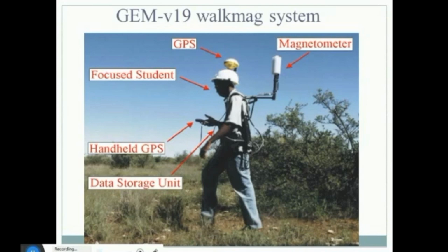Whereas it's the older magnetometer, which you also have, and you also use a pencil, you have to walk 5 meters, put it down, take a measurement. Walk 5 meters, put it down, take a measurement. You can't have anything magnetic on you. I, by accident, once did a survey with a hat that had a magnetic rim, and I didn't realize it, and the data was a disaster. So we had to redo that one.